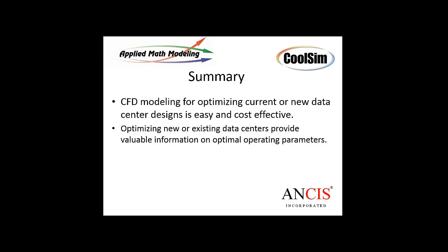Most equipment, it's safe to use 20. Now, a lot of these new servers are claiming 30 and a little higher, but that's being a little aggressive. 30 degrees across a server, yeah, they can handle it. Do you want to run there? You can certainly try it. The program, CoolSim, is adjustable. You can adjust it to 30 or whatever you want. I tend to run 20.